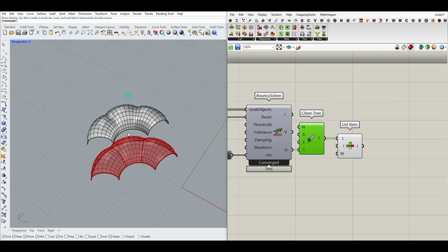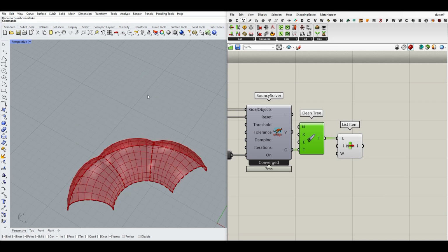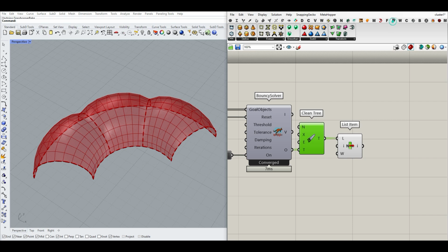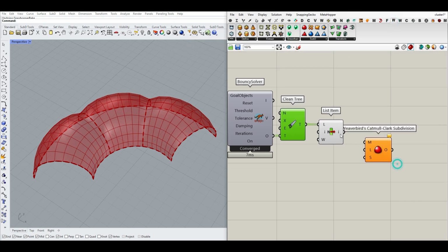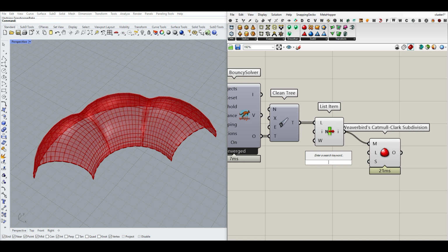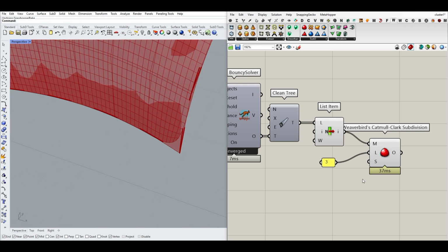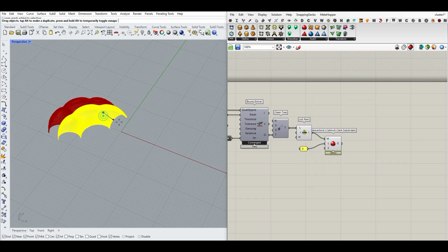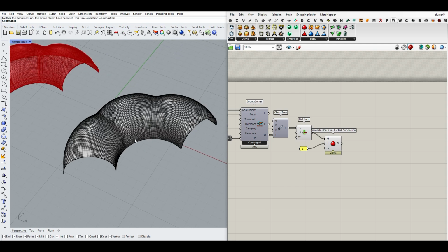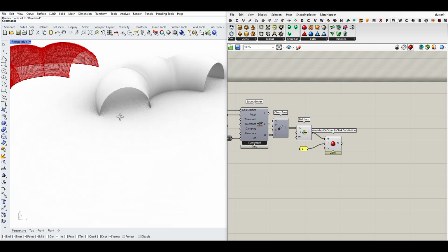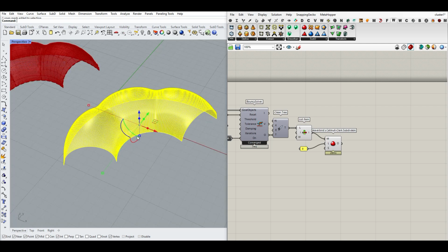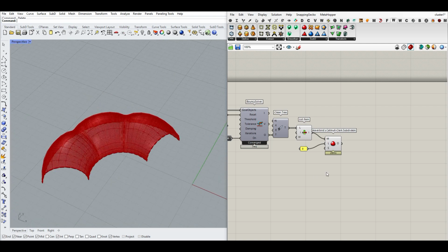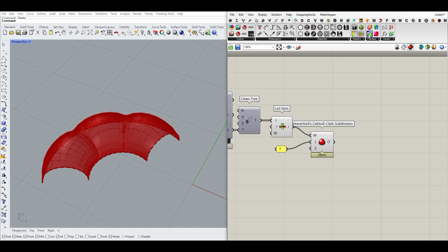The resulting mesh. You can also use the Weaverbird plugin. For example, I can use the Weaverbird plugin and use the Catmull-Clark subdivision and maybe just put this to 3 times smoothing. And also use the corner fixed as an output. So that is also a smoother mesh if you want. As you can see here, if I go to the rendered mode, obviously, you can see that here. So, for example, if I want to see that better, I can use a custom preview